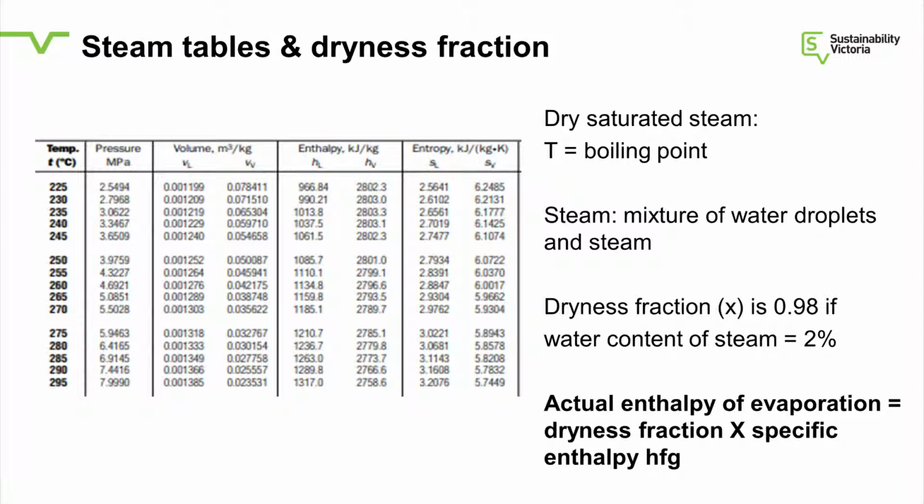If you look at the steam tables, which are commonly available in the literature, what they do is basically show you what pressure you need. If you look at a typical table there, at what pressure you can provide the temperature of the steam at. So it's a very predictable thing. It's also good, it tells you the volume, in other words, the metre cube per kilogram of steam, so it helps you size the pipes.